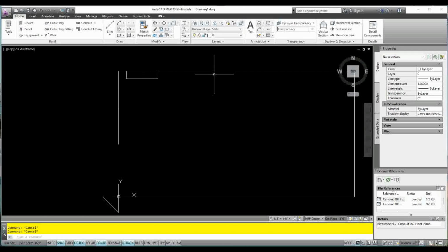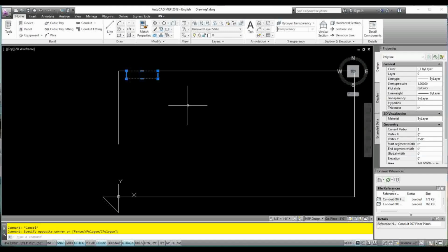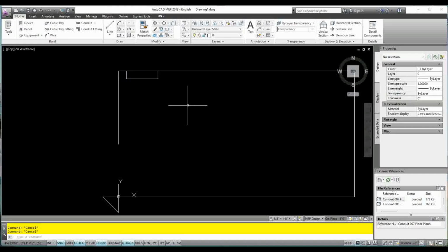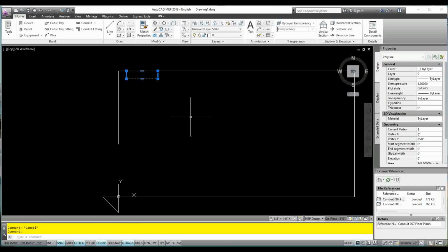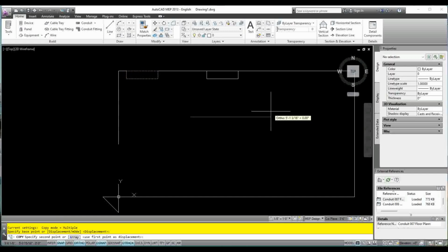What do we got over here? How about we have another panel? So we've got to create another one. Type in REC, and touch that corner. We'll pull it out, and once again, we'll go dimensions, enter. Actually, we don't need to do it that way. I kind of messed up. Just highlight it, and type in copy, C-O-P-Y, enter. Click on the screen, pull it over.